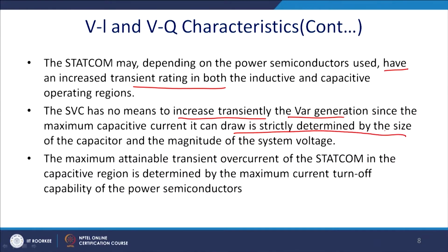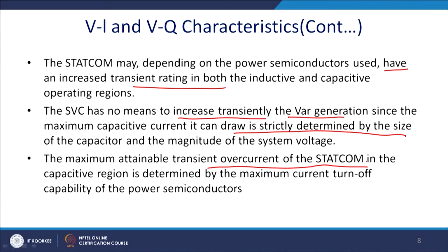SVC has no means of increasing the transient var compensation, since the maximum capacitive current it can draw is directly determined by the size of the capacitor and the magnitude of the system voltage. So, the thyristor is almost a passive device here. The maximum attainable transient overcurrent of the STATCOM in the capacitive region is determined by the maximum current turn-off capability of the power semiconductor, but in most cases it will be determined by the capacitor rating